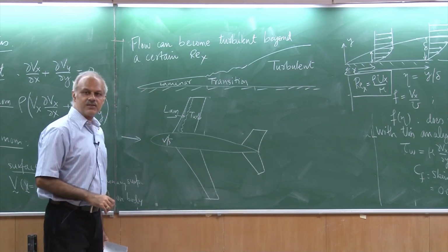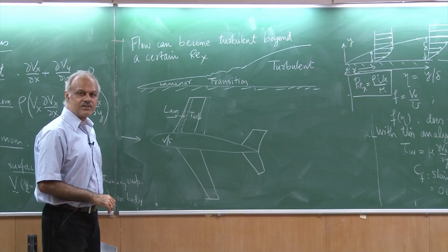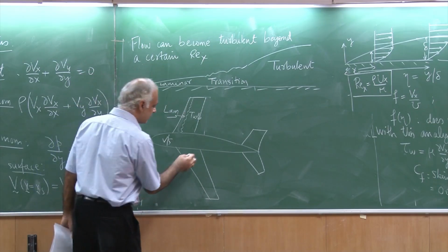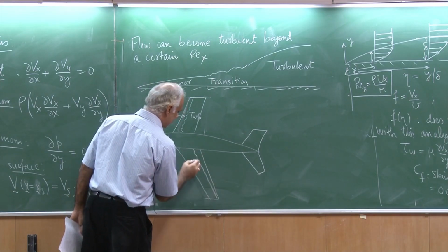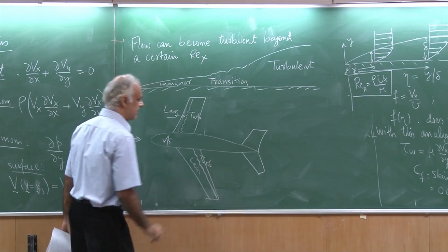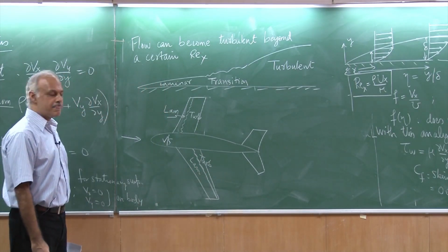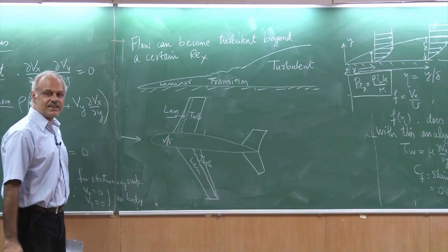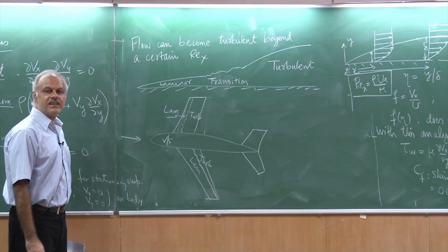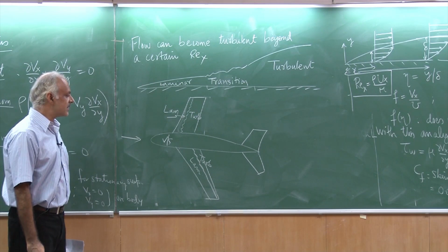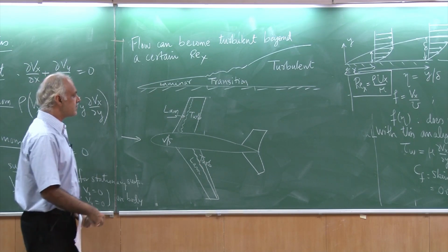Versus if I polish or wash my aircraft nicely before another takeoff, keep it clean, it's possible that I may get laminar up to a long point and turbulent a little bit later. So we have not changed the design of the aircraft, we have not changed anything, but simply by maintaining your aircraft clean, you can actually affect the transition point and save on the fuel.